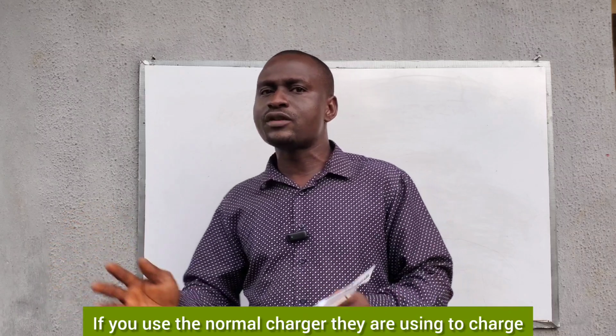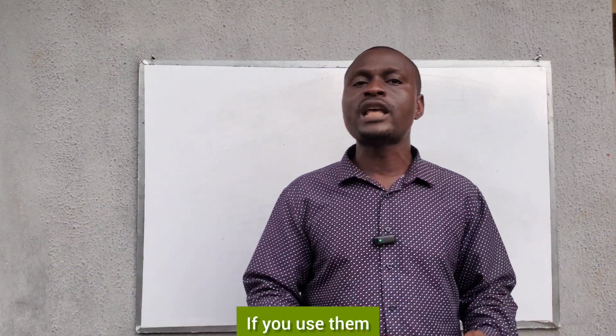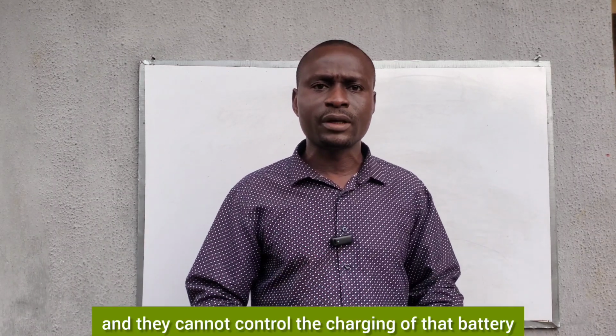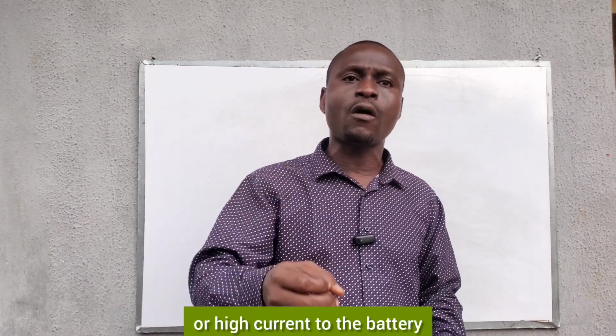deep cycle battery. If you use the normal charger that electricians are using to charge car batteries, most of them will destroy your batteries, because they cannot regulate and they cannot control the charging of that battery. So even when the battery is full, they will still be sending high voltage or high current to the battery.